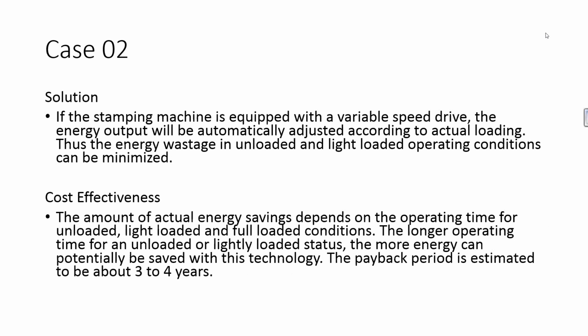The solution for this: if a stamping machine is equipped with a variable speed drive, the energy output will be automatically adjusted according to the actual loading. Thus, the energy wastage in unloaded and loaded operating conditions can be minimized.